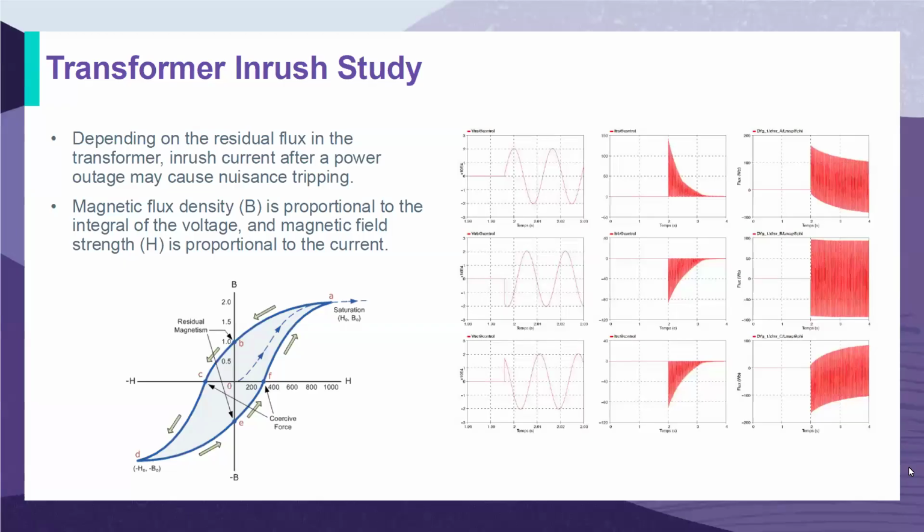One of the studies that we've added was the Beaver Creek Solar Project. Take the inrush current, for example: the load in Beaver Creek was something like 300 to 500 kilowatts, and they're implementing a 1.5 MVA transformer in the system. The magnetization of the transformer will require some sort of inrush current that the system wasn't necessarily designed to accommodate. Will it cause nuisance tripping by magnetizing the transformer? I'm not going to get into this right now, but if you want to nerd out with me afterwards, I would love to talk about this study as well.